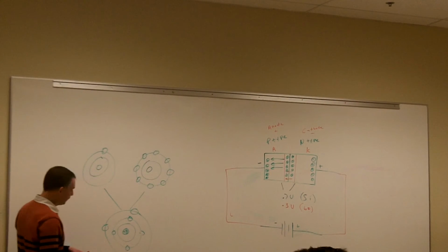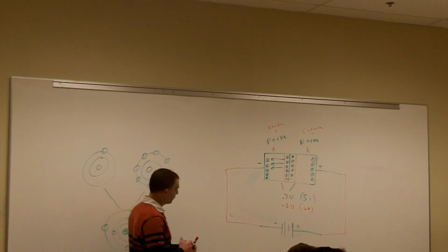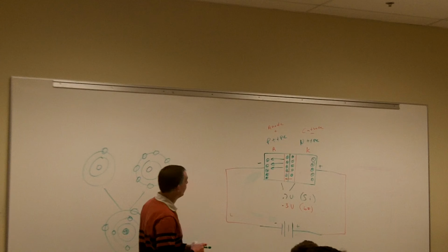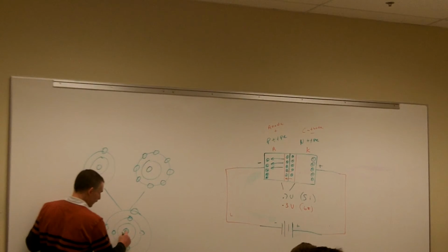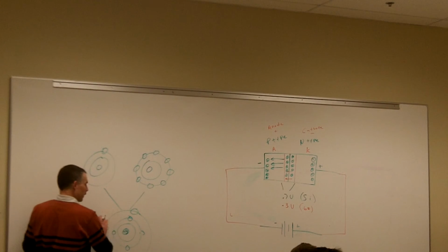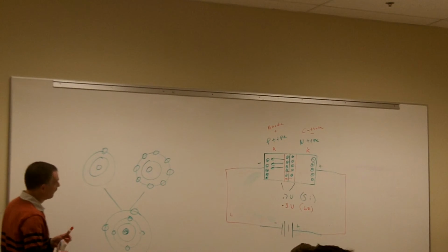So that would be a P-type material. That gets complicated, but that's how you figure out whether it's a P-type or N-type. If it was an N-type, then this atomic number would have to be a 15, where I have 5 electrons on my valence ring.